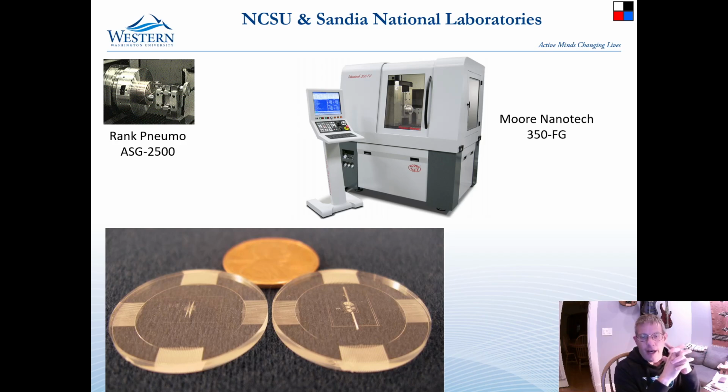And so I had to make a fixed ring system that would move this thing across the face of this machine tool to be able to create each of these little lenslets at the center of rotation, and have them all so that every lenslet was within 1/100th the diameter of a hair in X, Y, and Z from any other lenslet on the whole thing. So a really neat project. About $60,000 to create the first one. They got a lot cheaper after that, but just developing that process.